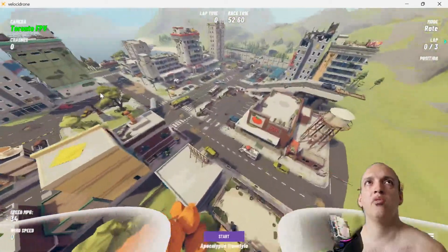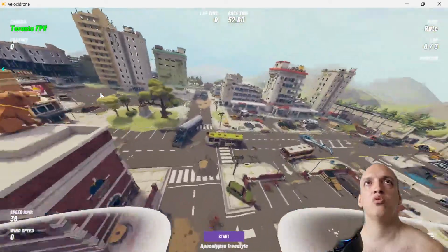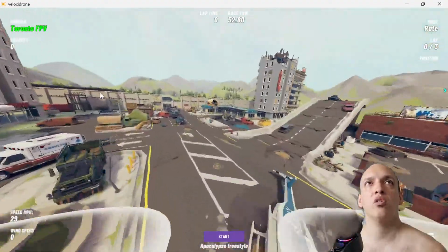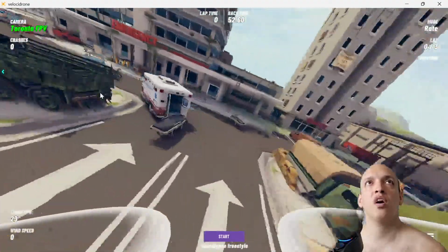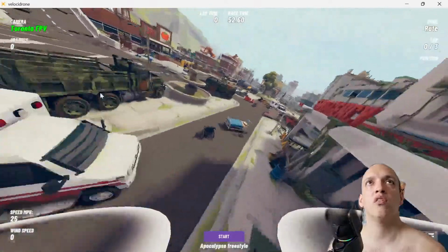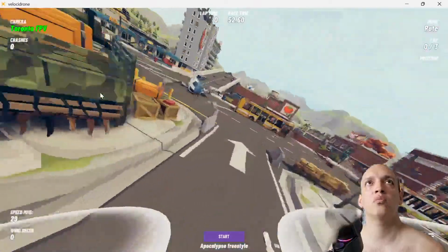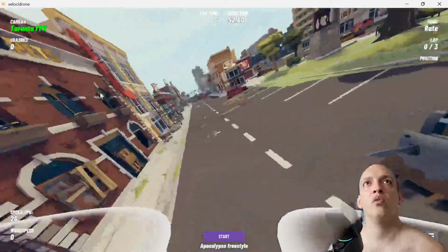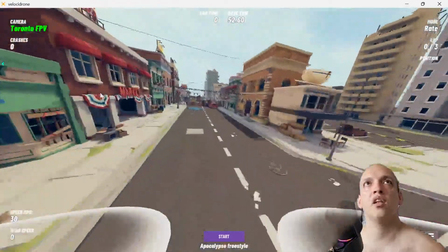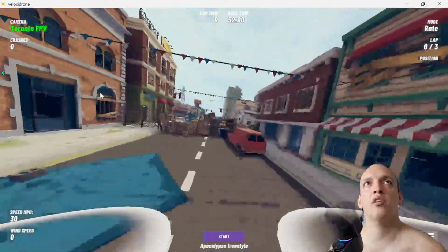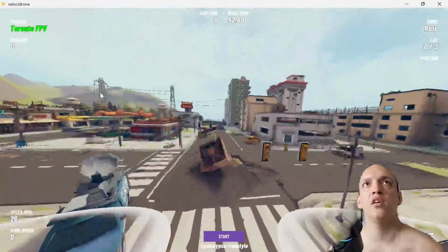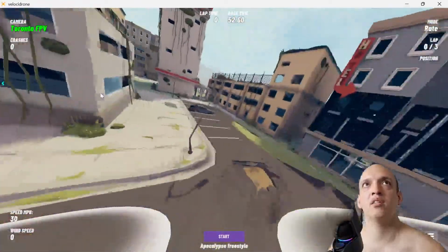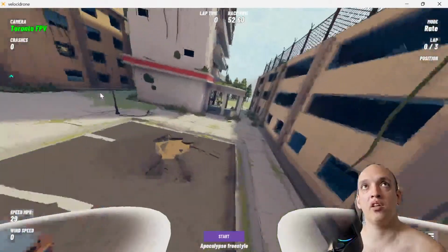And just get used to these movements and get used to controlling your drone. Do it up high first, and then start slowly bringing yourself to the ground and just follow the road. Start following these roads. And then use those sticks together. Woo! And then that gets exciting. Kind of lower is a bit more exciting, but there's a lot more stuff that you can hit. So you want to start high. You learn all those movements, and then you start coming low. Then you can start flying through things.